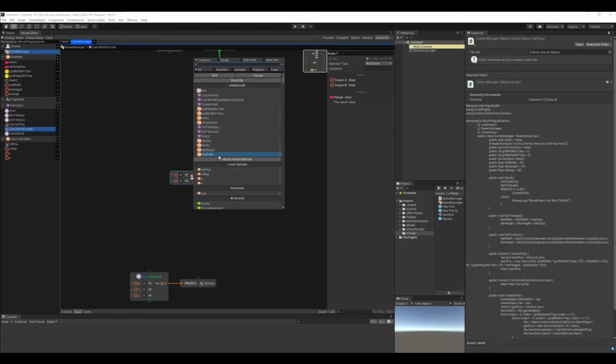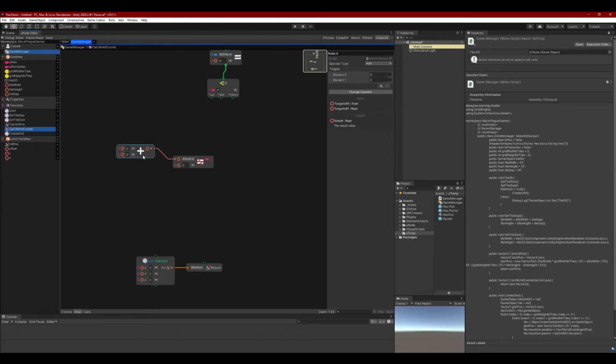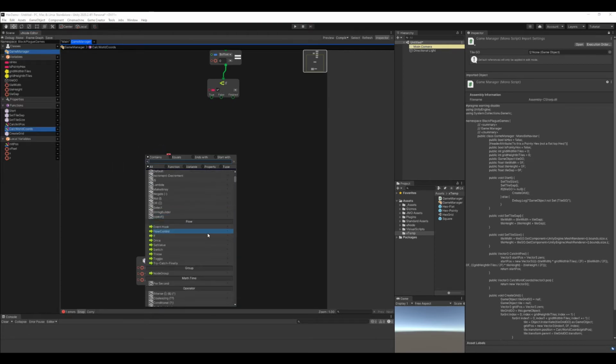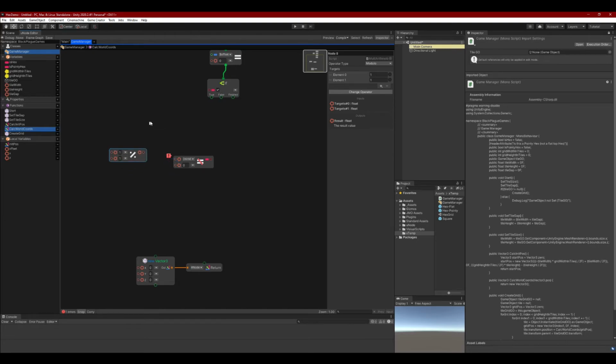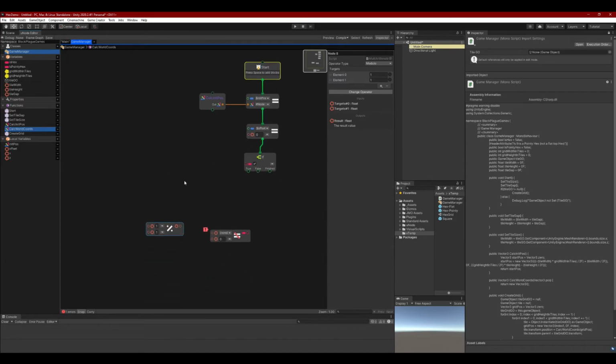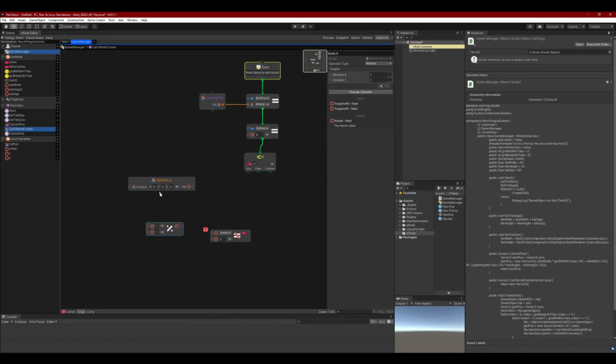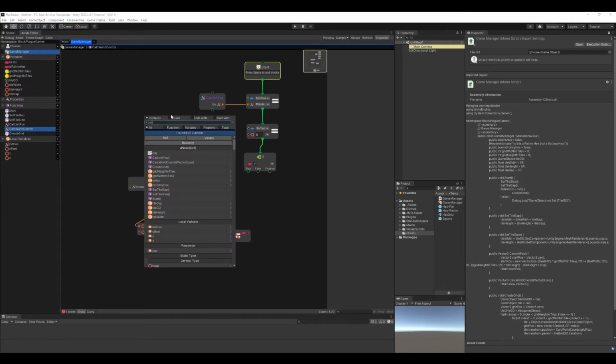So first thing is we're going to go ahead and grab a not equals, and then we will use the mod or modulo option here. Let's see if we can find it. There we are. Kind of working backwards to construct this, see how it works out. So we'll need the vector3.z. That will be plugged into the mod. The mod will be plugged into the does not equal. We'll have a 2 in here on the mod. So this is the logic for hexes in general.